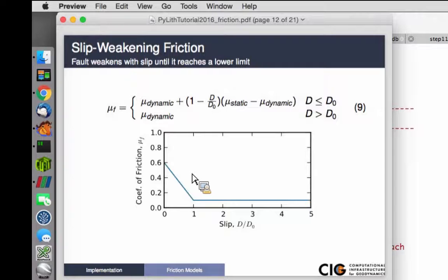So that's what this D is, remember this is just a scalar for the coefficient of friction. As the slip accumulates along the path, it's integrating the distance along that path. It is comparing that to D0 to get down from the static coefficient down to the dynamic coefficient of friction. Once at a time step it's locked back up, it resets the accumulated distance along the slip path.